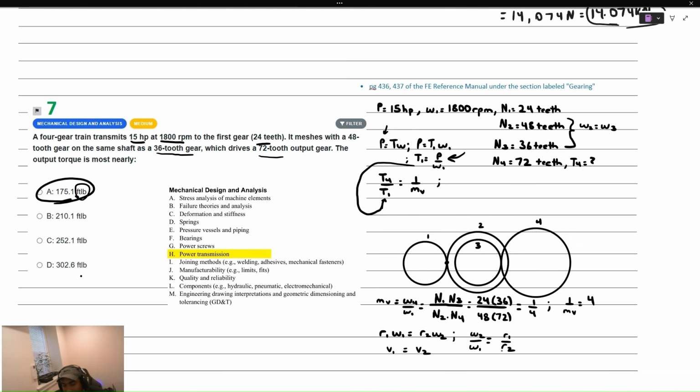Okay, so that is the ratio of pitch radii. That's also equivalent to the ratio of pitch diameters and also equivalent to the ratio of the number of teeth. All of these things are related via constants, and when you multiply the top and bottom by the same constant, they end up just crossing out. So that's why this relationship is true.